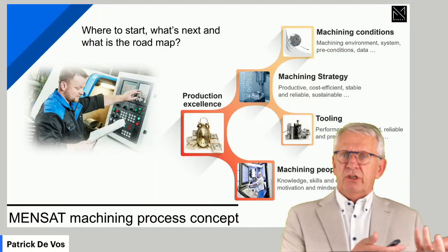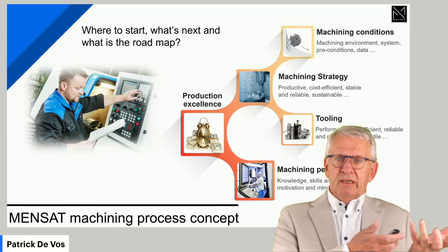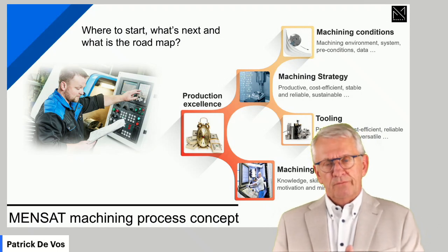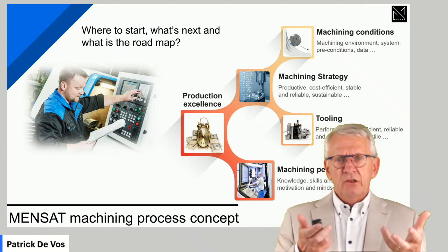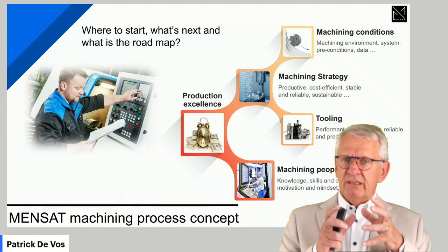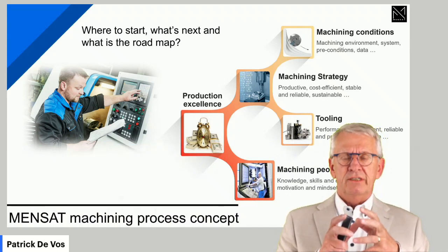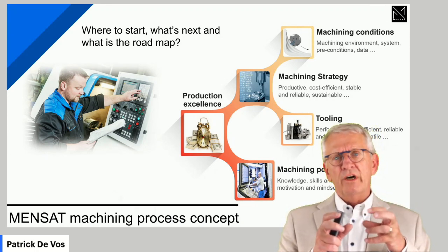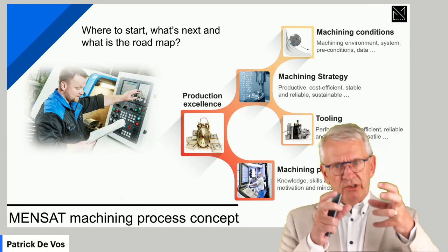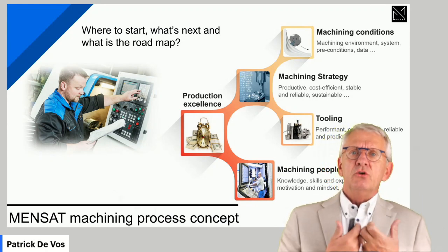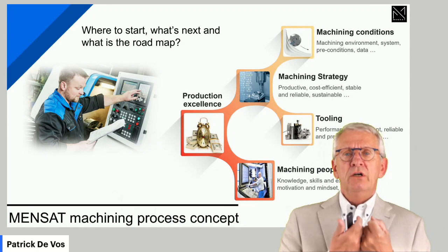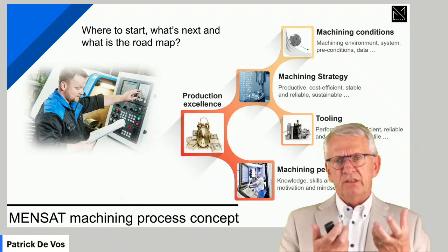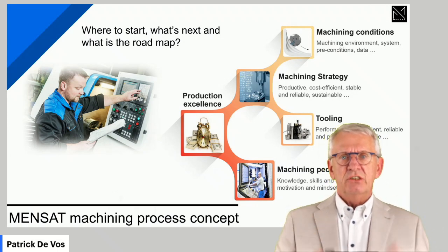I can reverse things. If you select a cutting tool, well, to use the cutting tool in the best possible way, you need to use a certain machining methodology. So it's all about, also here, a balance. Well, and machining data play a major role in this, because to bring a strategy and a tool, whatever came first now, not important, to make the combination work, that's what we do with machining data, with cutting conditions. So it's the linking element between strategy and cutting tool.